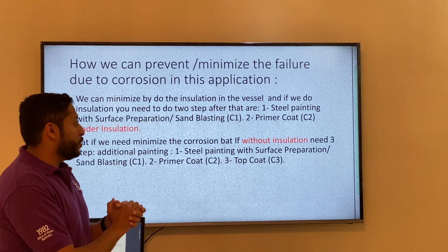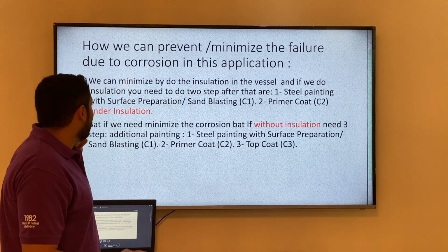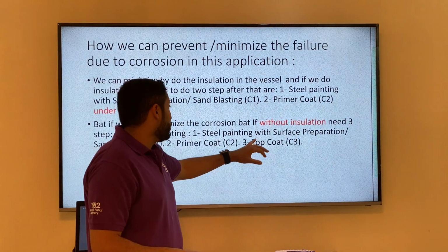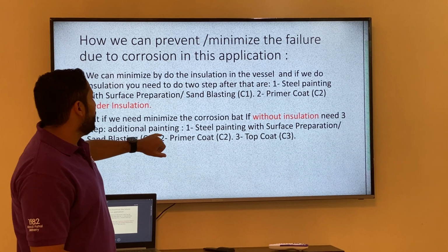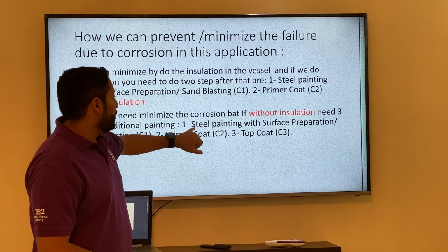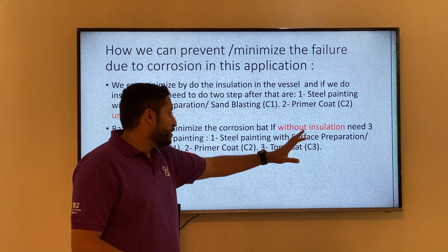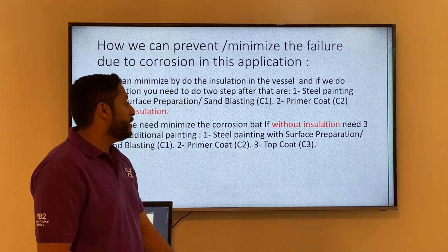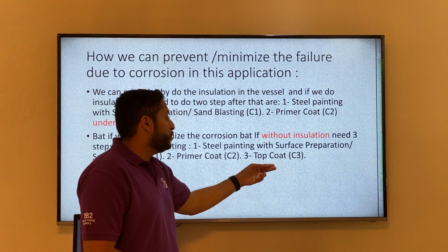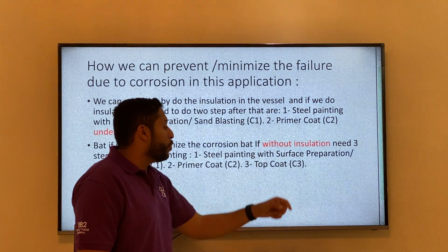Okay, if I don't do insulation, there are three steps. Without the insulation, we need three steps: painting with the surface preparation like the first one, the second is the primer coat, and the third one, if I don't use the insulation, is the top coat. Okay.